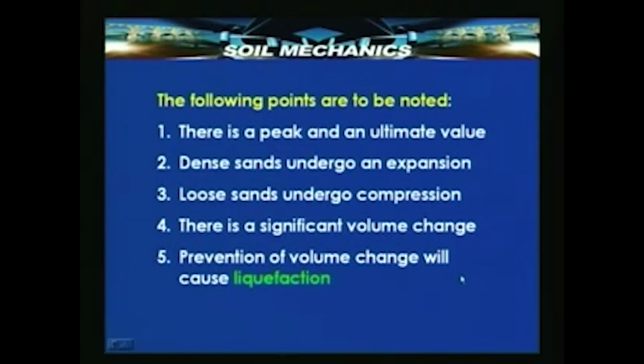Prevention of this volume change is not going to permit development of the effective stresses and the friction angle, and therefore it will lead to a kind of failure which arises because the soil now behaves like a liquid. Shear resistance is not allowed to develop due to volume change prevention, and this phenomenon is known as liquefaction.